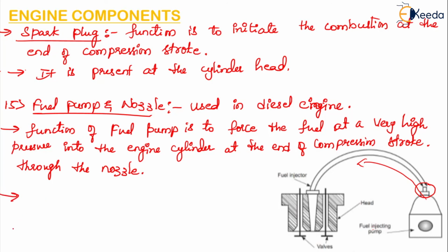Now, what is the function of the nozzle? The function of the nozzle is to break up the oil into a fine spray into the engine cylinder at the end of the compression stroke. High pressure fuel is sent into the nozzle by the fuel pump, where the nozzle will break the fuel particles into spray.